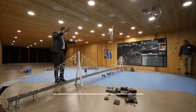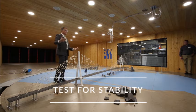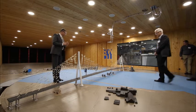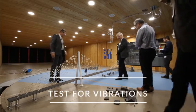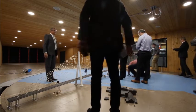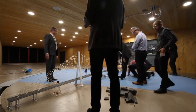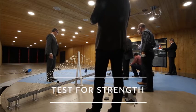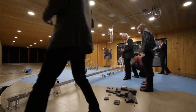Today what we're testing really covers three areas on the bridge design. One is the overall stability of the bridge against high wind conditions. The second is to make sure that under normal everyday wind conditions we don't have vibrations that are going to make the bridge uncomfortable for the pedestrians. And the third is under relatively high winds, from a buffeting standpoint, to make sure that we have enough strength designed into the bridge to carry the wind loads.